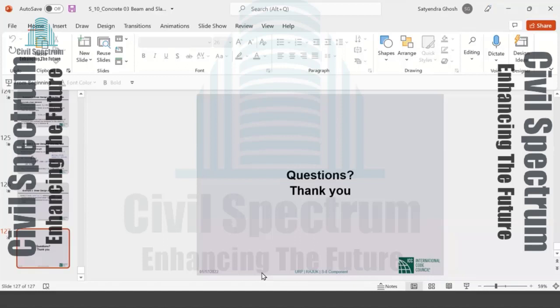Wrapping is almost exclusively a retrofit measure after something has happened, to restore shear capacity and so forth. Wrapping is quite effective.